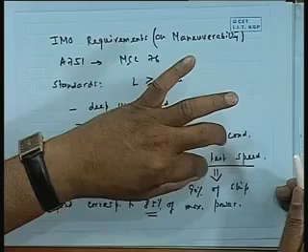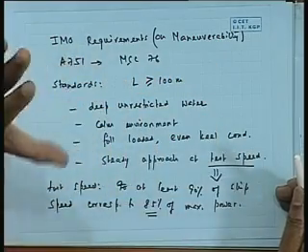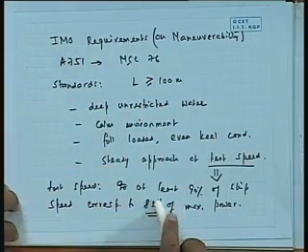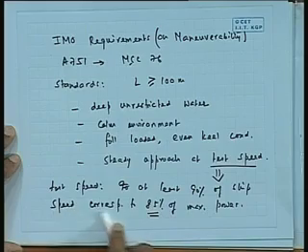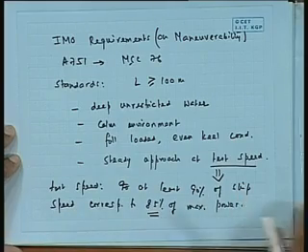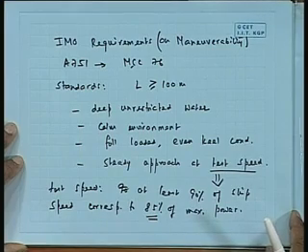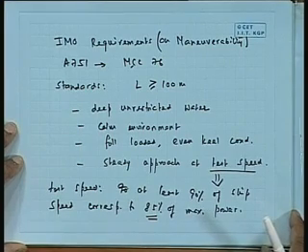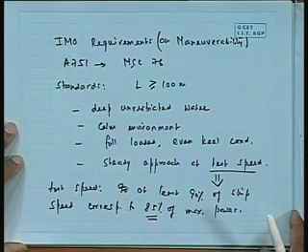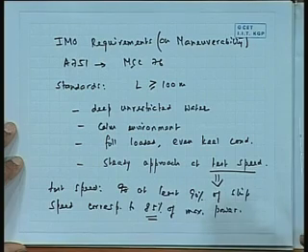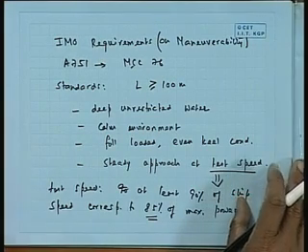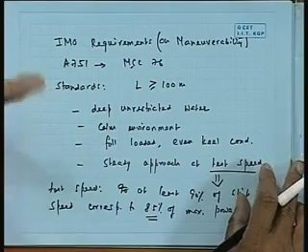The speed should be at least 90% of the ship speed corresponding to the 85% of power. At 100% power, what is the speed? That is 85% of MCR. Exactly. MCR, and what is that? 95% of the ship speed, 0.9 of that. Basically, it specifies a lower limit of speed. It must be at least at that speed. So you can calculate that.